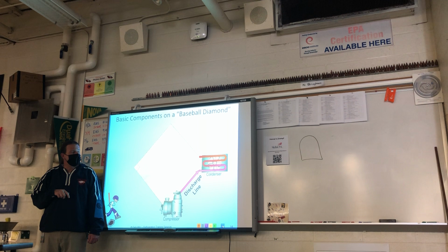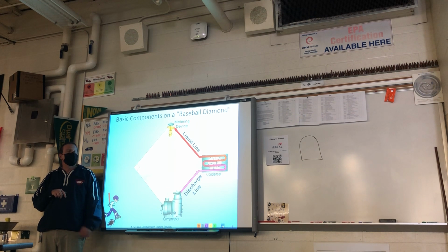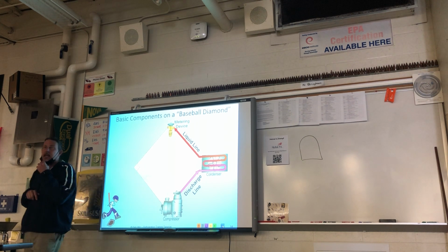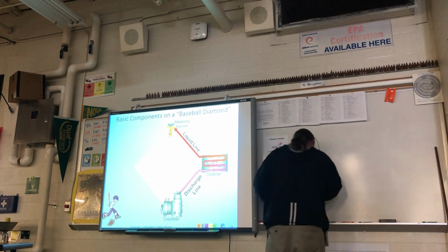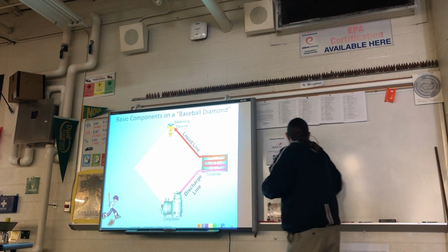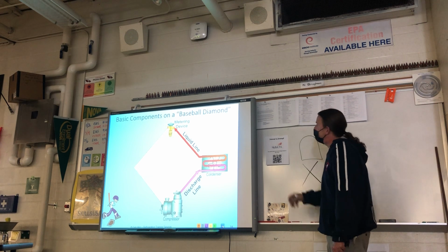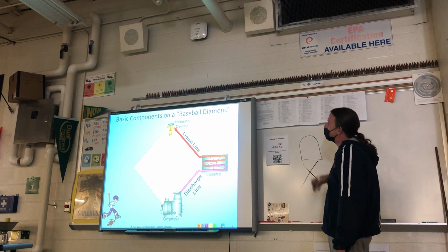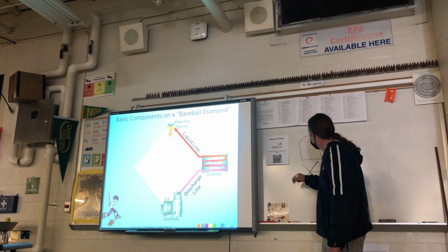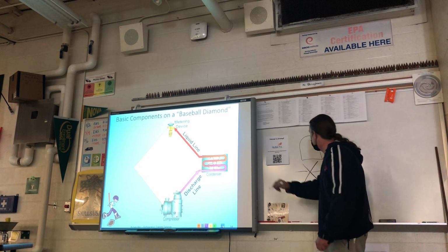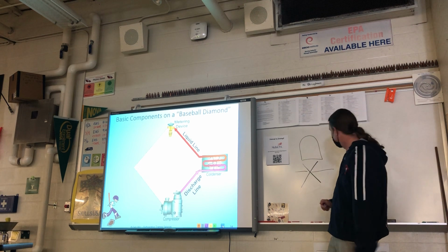What did the condenser reject the heat and give us? Liquid. So yes, the liquid line feeds into our metering device. And I like to draw the metering devices like an X. I don't think I'd draw the fancy one. I would just draw an X because it comes in, it restricts, and then comes out, in my opinion.